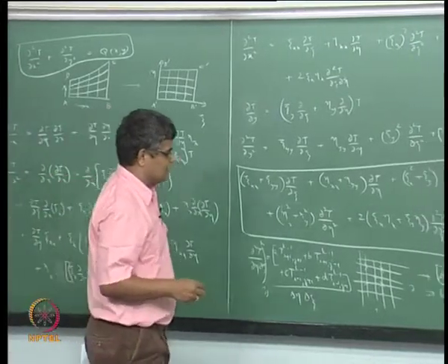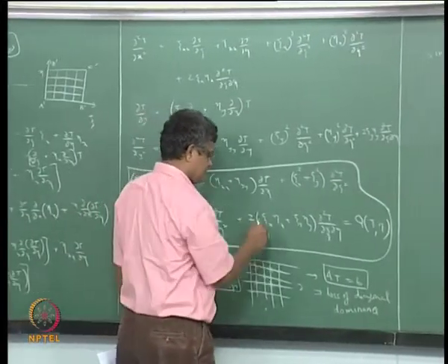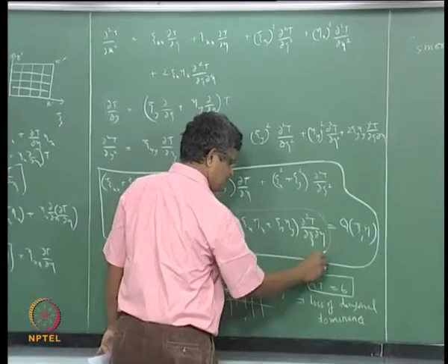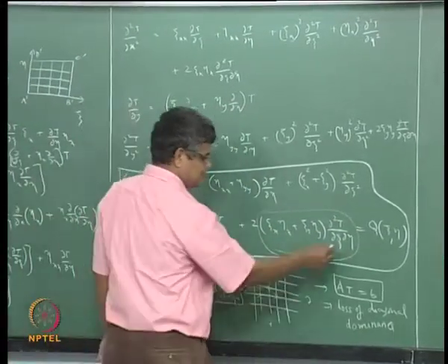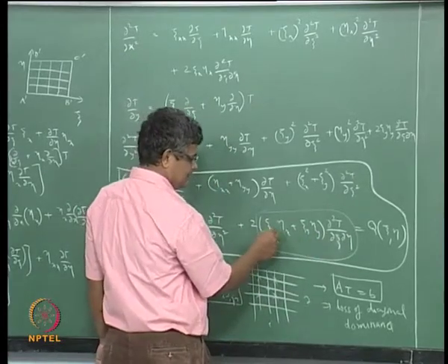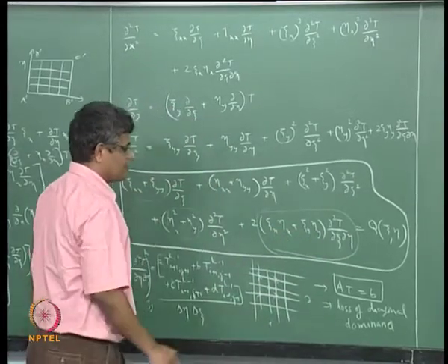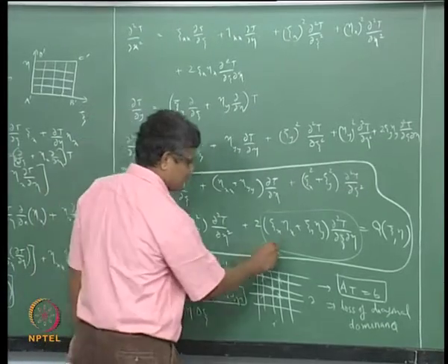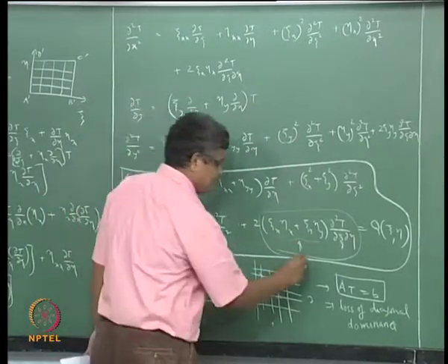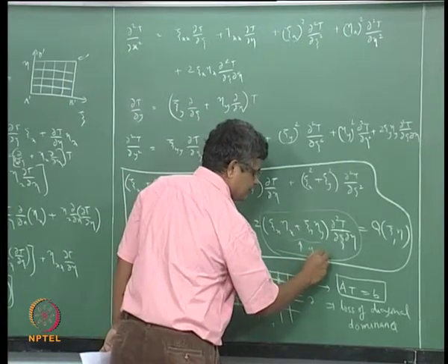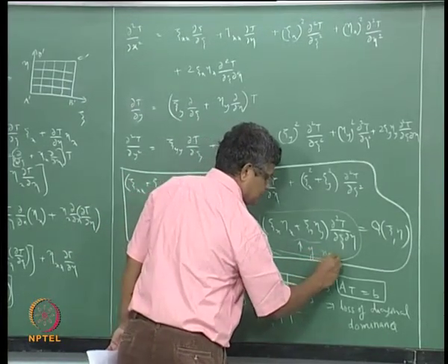And the most important problem is also with respect to the appearance of the cross derivative, and this cross derivative is multiplied by these metrics here, and the contribution of these metrics, these terms, will be higher if you have a non-orthogonal grid.